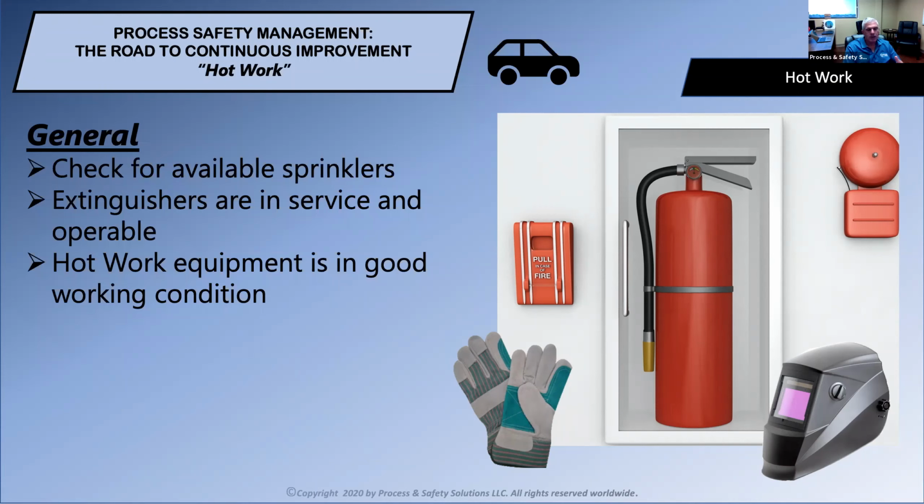Also making sure that any cutting torches have properly maintained hoses, that the torch itself is properly maintained, and that it can shut off gas, both the fuel gas and oxygen. For grinders, make sure all of the guards are in place, that the electrical wiring is not frayed, and that it's properly grounded, with all of the ground plugs in place and properly connected.